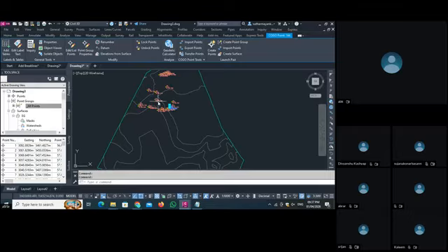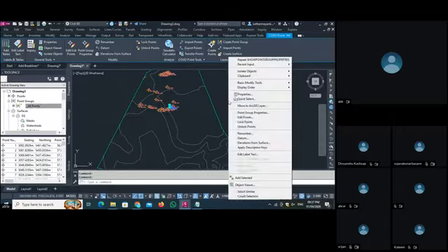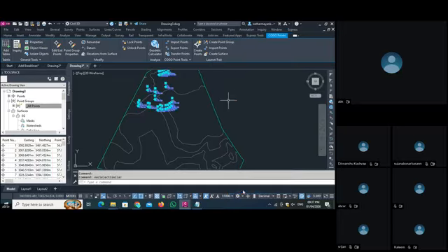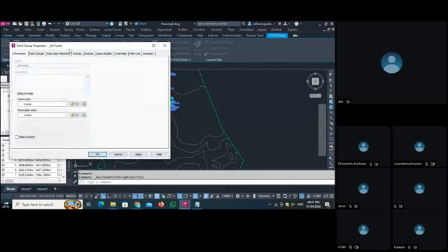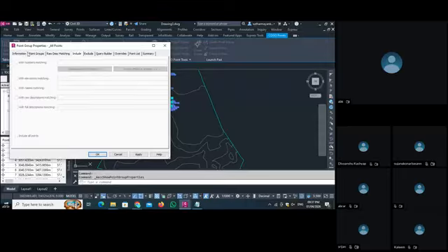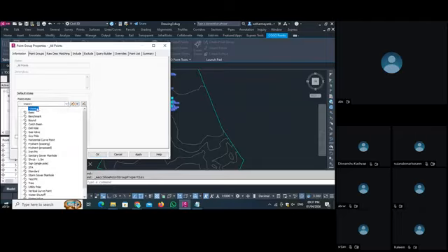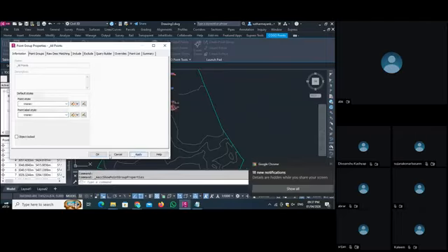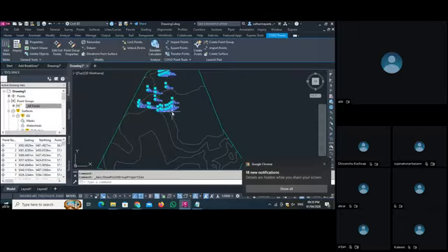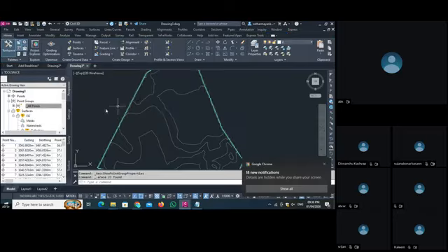This is another point we added as vegetation. What we do, we select one point, right click here, and select Similar. Click on Select Similar, so all the similar things are selected. Then we go to the point properties here, and in point properties we can set all the things as none. So actually this is not a part of that, so that's why.